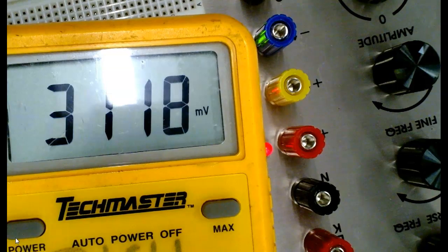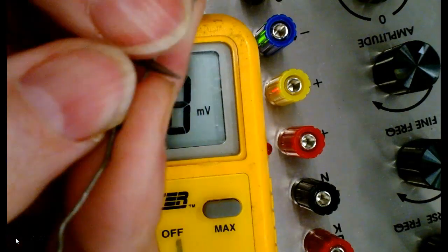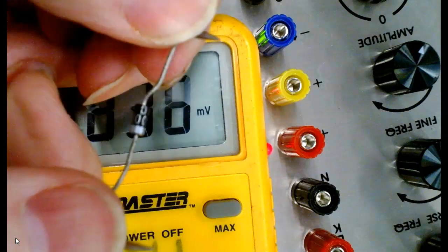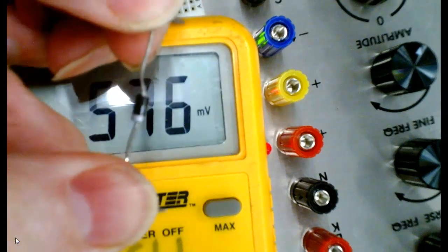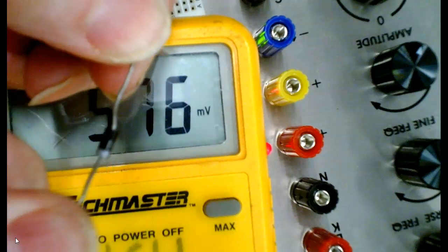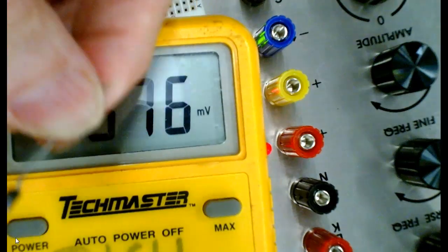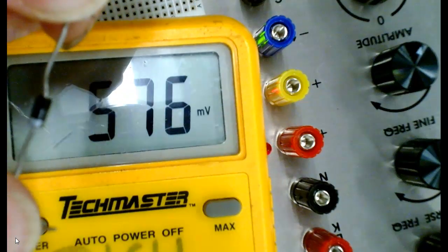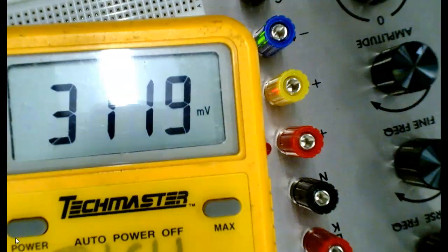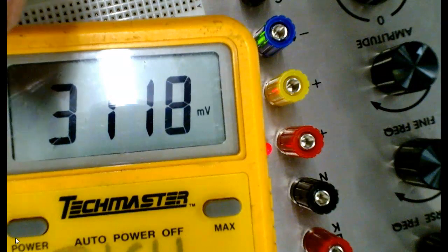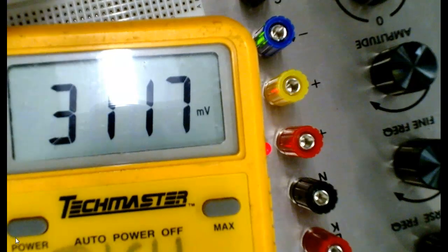And then I come up here and hook it up. So that would be this direction right here, with my black lead toward that stripe, and then my red lead on the other side. And this meter doesn't show overload on this, by the way, but notice here it's not going to change. So your meter will probably show an overload.